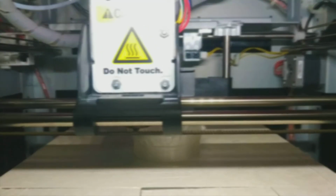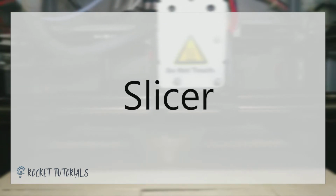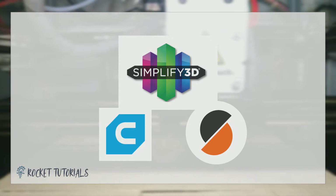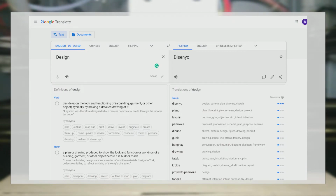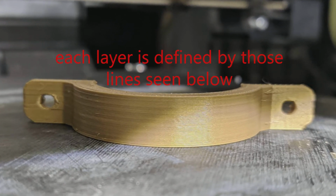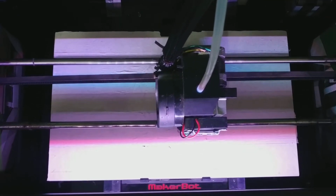Next in the list is the program, or what we in the printing world call the slicer. Basically, a slicer is just a CAM software targeted for 3D printers. Simply put, a program to interpret the design into the language of the machine. The idea is to slice the object into layers, thus the name slicer. Then what it does is it maps out movements per layer from the first to the last.